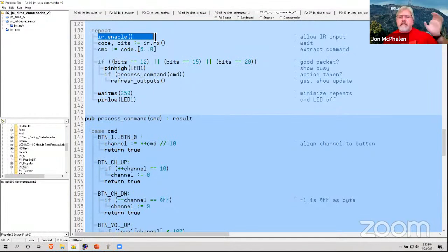So what happens is that I have to receive a number of bits to determine whether the packet is a shot packet or a data packet. Once I know what it is, I can alert the foreground in 2 different ways. There are 2 different data packets, though. There are what we call referee packets. So if a kid's out on the field and he's struggling because he's getting shot a lot, what I'll probably do is give him extra life points. That's one of the commands I can dial up here. There's a little user interface here, and I can shoot him and give him extra points. That's usually a 3-byte packet.